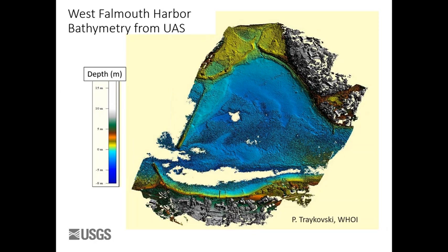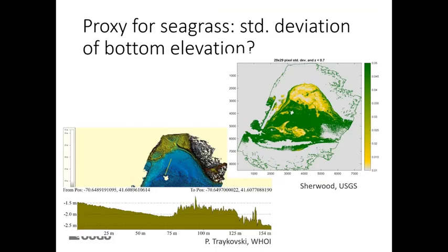You do. So what a rolling shutter is, like a regular digital camera will open the aperture and the whole CCD will be exposed at the same time. With a rolling shutter, you're moving the light across the shutter as a function of time. And so this end of the CCD is not synchronous with this end of the CCD, which is a problem if your drone is not in the same place by the time it gets there, right? So rolling shutters are not as good, but they're still okay. They just kind of add some blur to it.